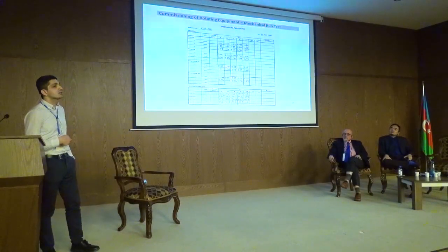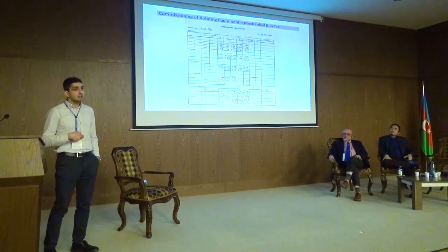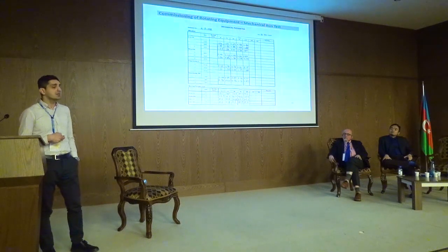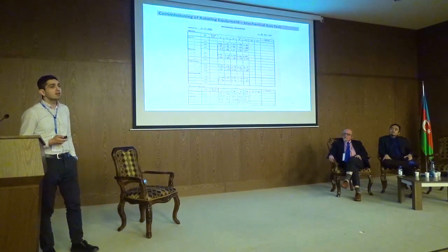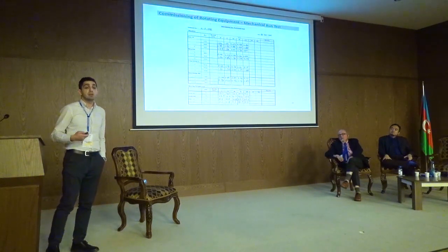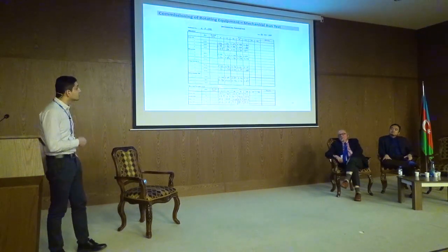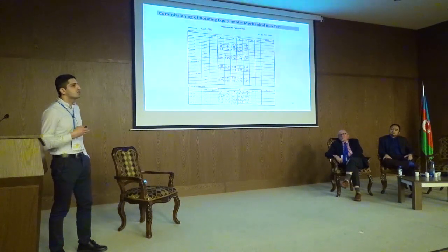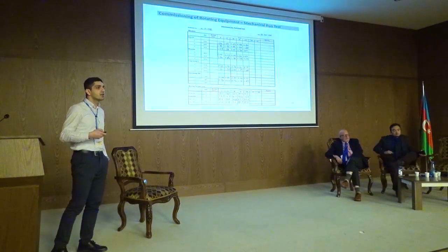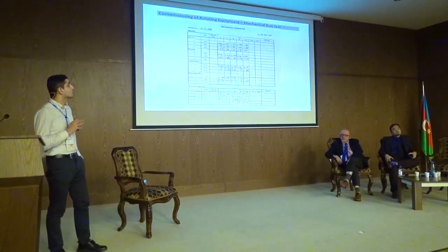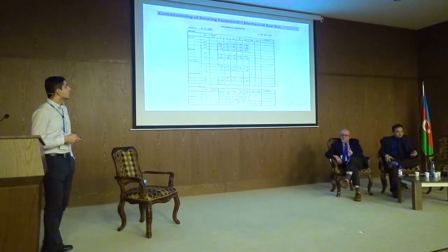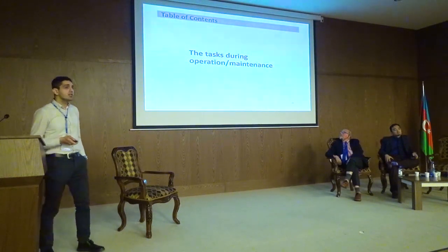These are not run under actual operating conditions, because we haven't started up the plant yet. We might not have the proper operating pressure and temperature available to do the performance test. So that's why it's just a basic mechanical run test, in order to see that the equipment runs smoothly. Okay? So once we are done with the commissioning, what is the next stage?